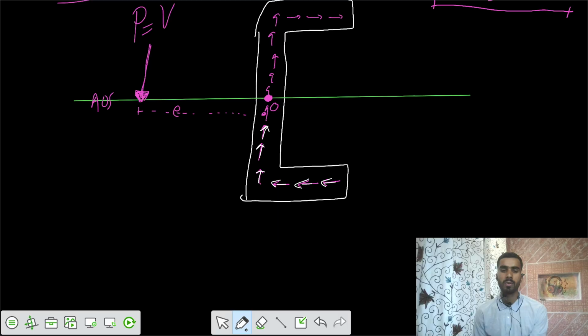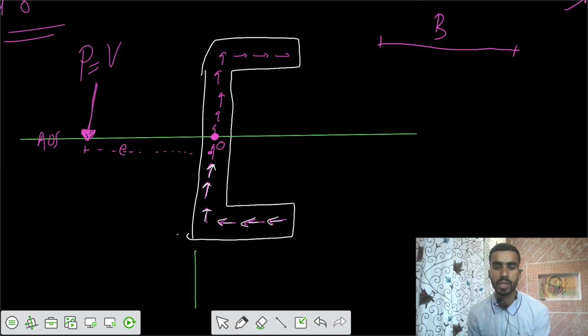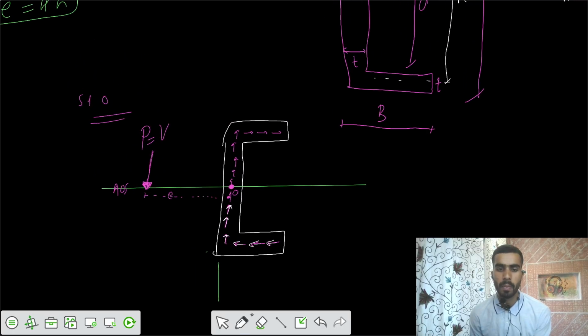From the shear flow, let's say there is some shear flow. How do you know the variation of the shear flow? Actually, what do you know about the shear flow variation? I know one thing, that the shear flow varies as z goes from 0 to some value of b. So we have a linear variation of shear flow from 0 to q naught.